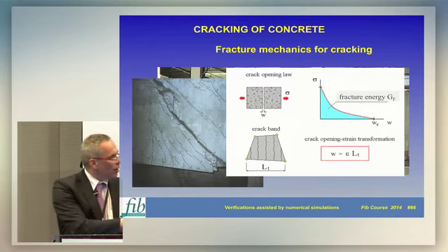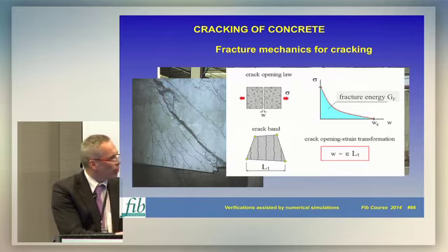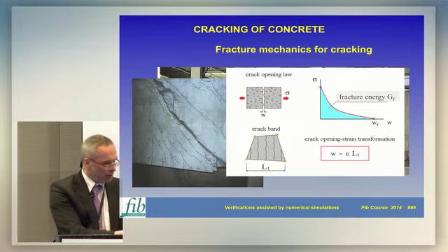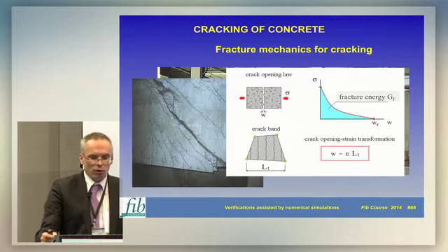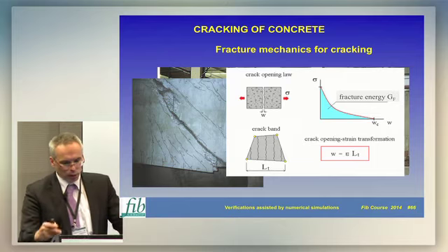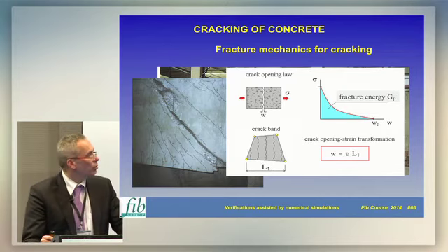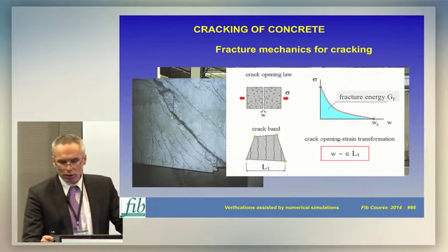And then this simple equation is used to translate the strains, which we usually have as our driving parameter inside each finite element, into crack opening displacements. And then we can go to the softening law for concrete, and in this way we can properly take into account the energy dissipation during the cracking process.